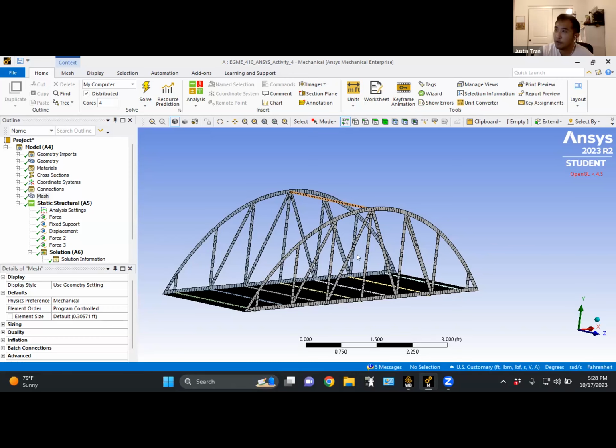Normally the conventional wisdom is that if you have a bridge that's higher up, then you would have higher wind speeds. But you can have situations where you have a lower bridge and your wind speeds can still be pretty high. For example, a bridge at the bottom of a canyon. In a canyon, you have this funneling effect with a lot of wind coming in through there, so you can still get high speeds and apply pretty high pressures.